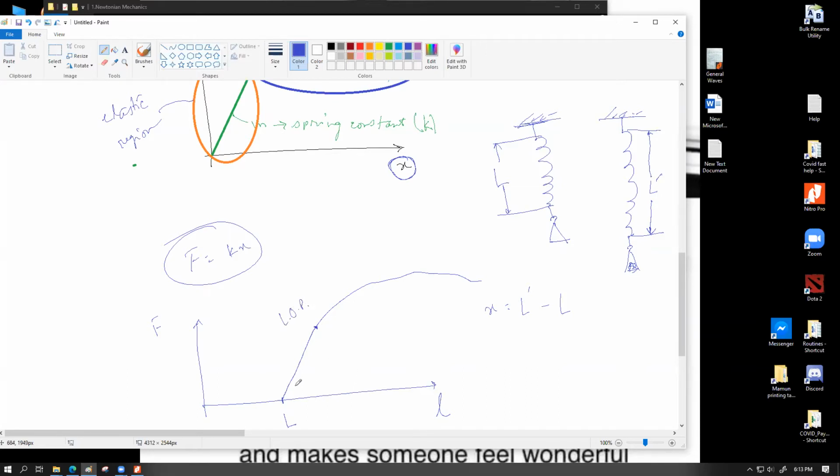In this case, this graph is not going to the origin, because this was not plotted for force versus extension. This was plotted for force versus length. So we have a bit of a dead space or intercept on the x-axis, because this part represents the original length, and from this part starts the change of length, or what you call the extension. This is important: whenever you are answering questions, especially the MCQ parts, be very careful to observe what the length axis is represented as. Is it the extension, or is it the actual length of the spring? These are the two variables you really need to take care of, so that you don't feel confused or miss out on marks.